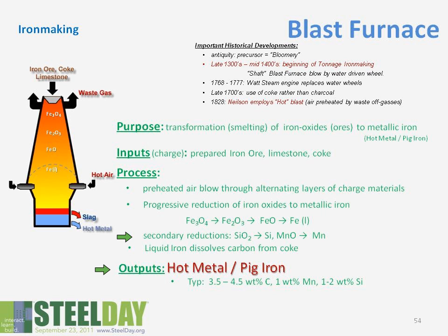So what you end up with is an output of hot metal in the liquid that goes directly to steel making, or you get pig iron, which is in the solid state. Again, high carbon, 3.5 to 4.5% carbon. No structural applications. It's really a feedstock for steel making.